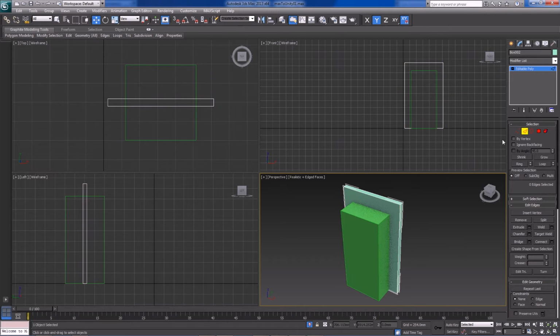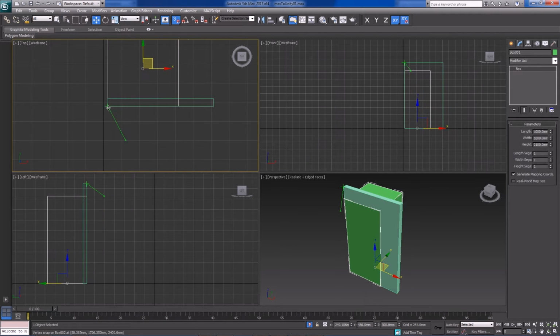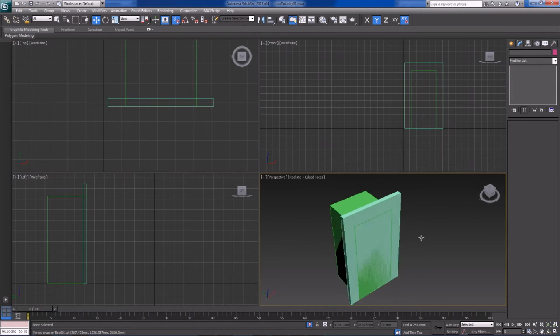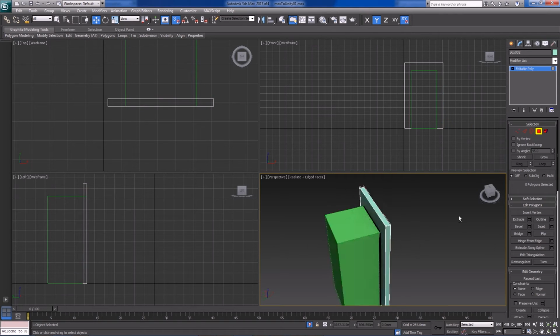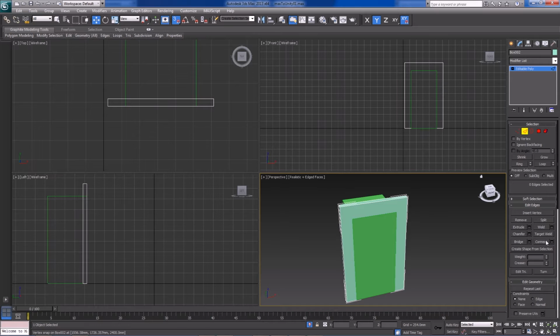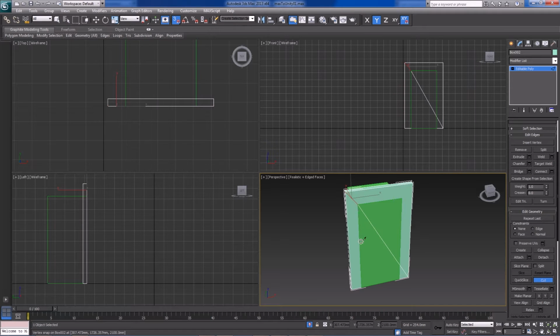Another way I could do it is to actually, just on the y-axis please, just snap this to here, delete the back face, just because we're going to be making cuts on this face, and then we're just going to copy this face to the other. So with our snap enabled again, click just to cut on our geometry. So there's one cut, there's the other cut, and our final cut is here.